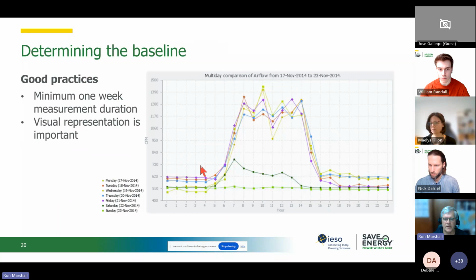And I calculated what the waste of that system is. 98% of all the air going into that plant is wasted because they leave the compressors on. So very nasty waste level in that plant because they really didn't get the memo, right? And they left their compressors on.